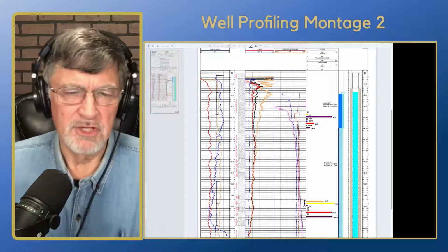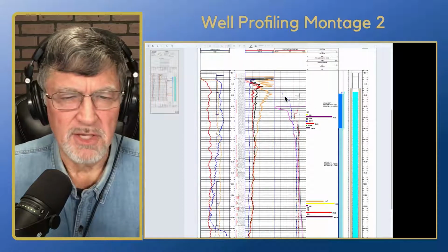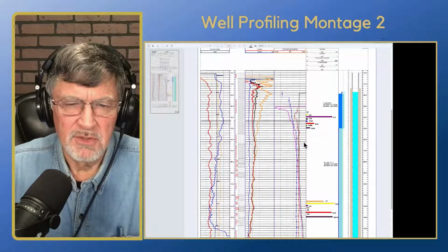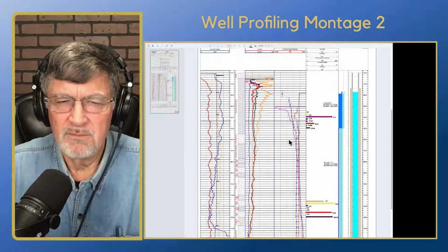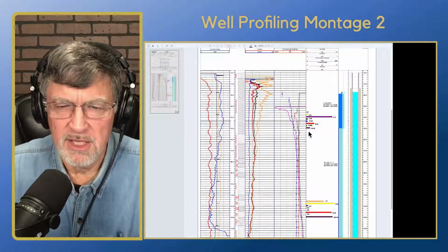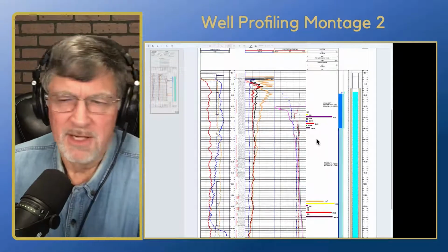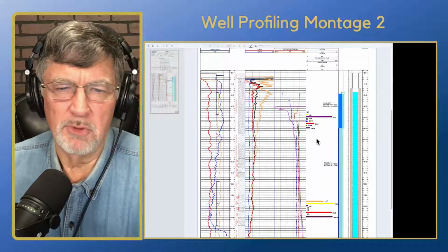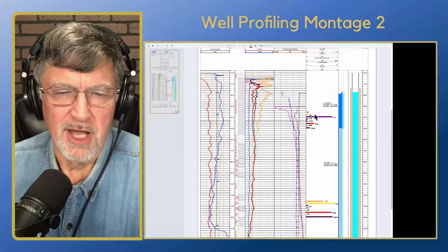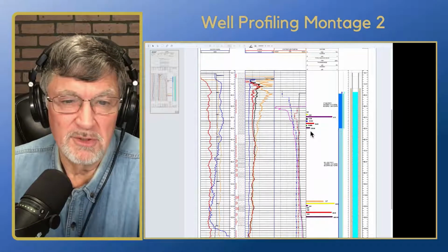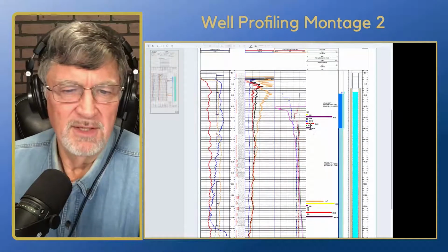So a very shallow well, but as you can see in our flow meter data, most of our production is by far and away in the upper 50 feet or so of this well. So we actually had to get special considerations to build this well with a really shallow seal in order to take this zone, because in California, the minimum seal is 50 feet.